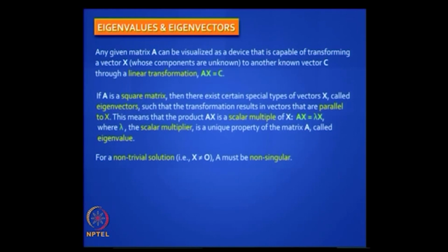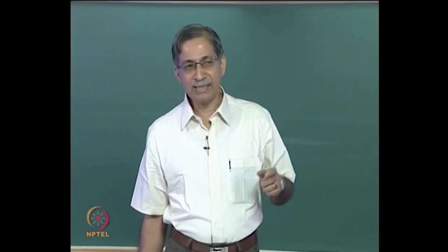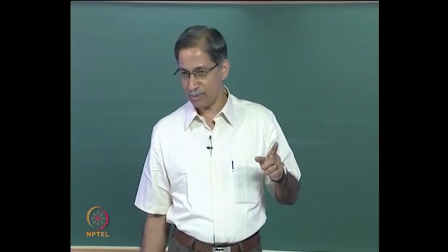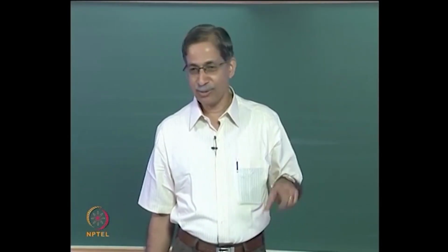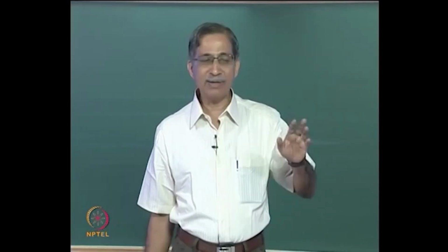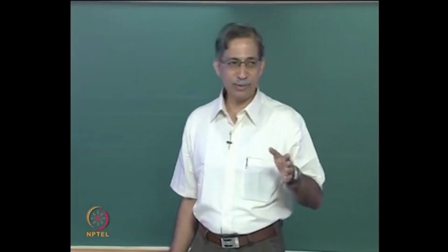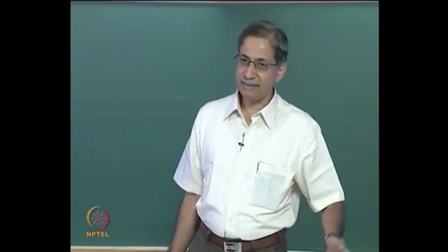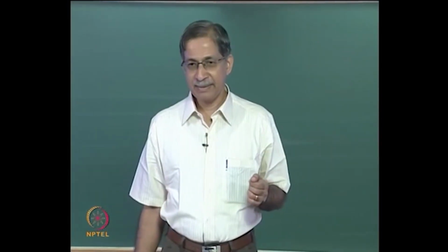The physical example that you can appreciate is the case of buckling. Okay, how do you get the critical buckling load? Well, actually, if you remember, you must have done the Euler buckling analysis. You write down an equilibrium equation, assuming it to have buckled, and you try to find P critical, which would facilitate that buckled shape.